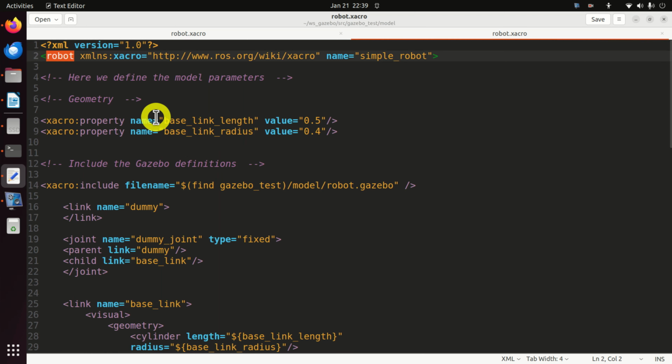Now, a good check of your URDF file is the following. When you open some environment, or this notation, if you start link, you need to end the link. If you start joint, like this, now notice what happened over here. We're starting joint inline, you actually have to again end joint.